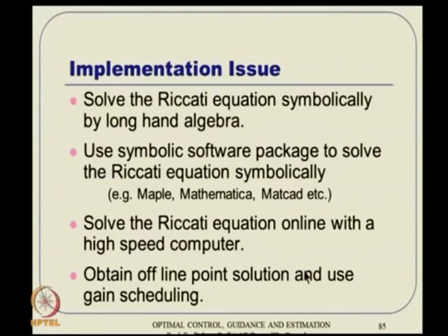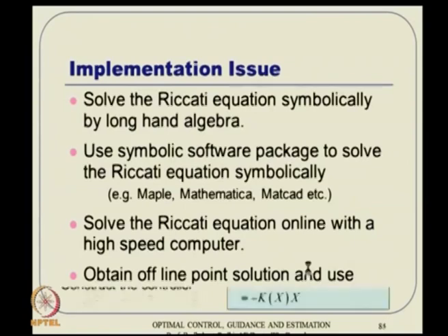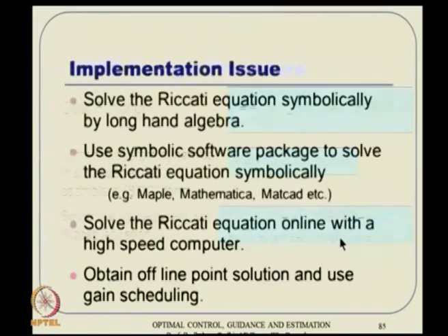And then there are implementation issues, because you are demanding an online solution of the Riccati equation. How do you do that? First of all, if it is possible, the Riccati equation can always be solved by longhand algebra, especially if it is a 2-dimensional problem. Sometimes people have done this for 2D guidance problems. They analyze the Riccati equation extensively in symbolic form itself and come up with a symbolic solution. That is the best thing if it is possible.